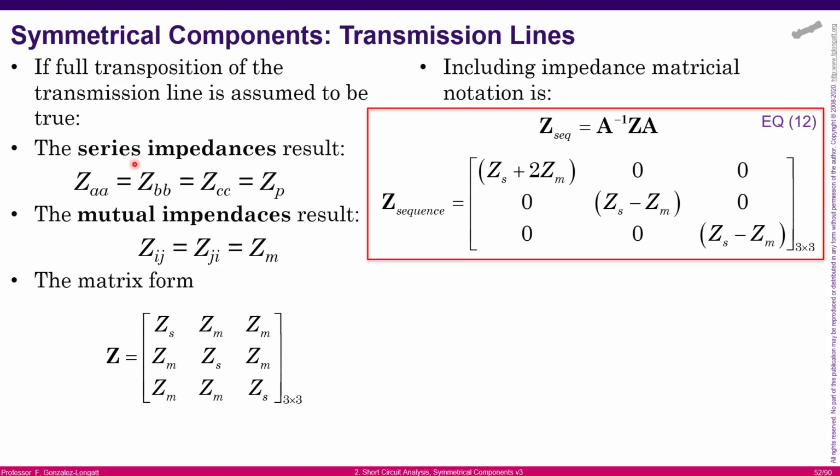What we need to understand is that typically in a transmission line, when we have mutual coupling, there are some properties that are quite typical. The property is that between A, B, and C, the self impedance is the same for lines A, B, and C. The reason is quite simple. The conductor is the same, and as a consequence, the magnetic influence over the conductor by the line current is the same. As a consequence, we can call this one Z_P, okay?